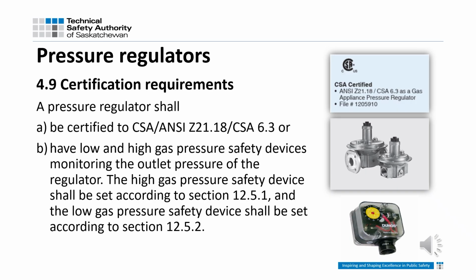4.9. Certification requirements. A, a pressure regulator shall be a certified pressure regulator, or B, if a non-certified pressure regulator is installed, that regulator, when installed on the appliance, should be monitored by both high and low gas pressure switches.